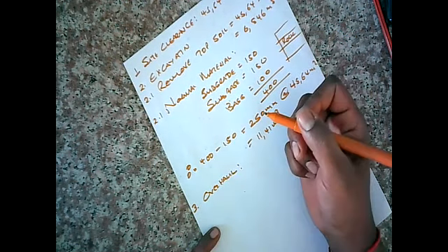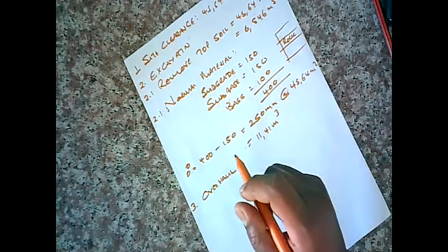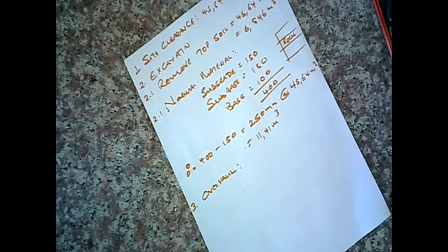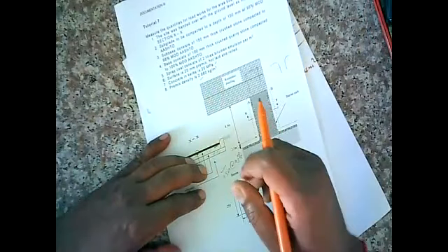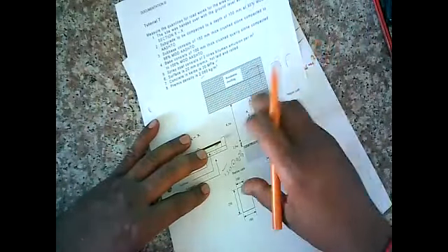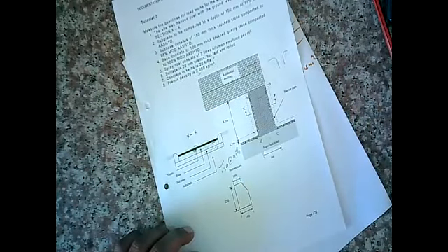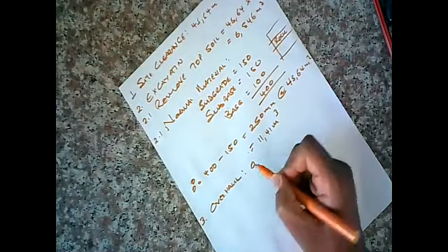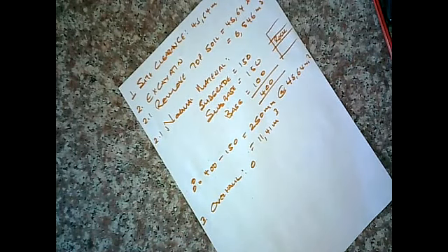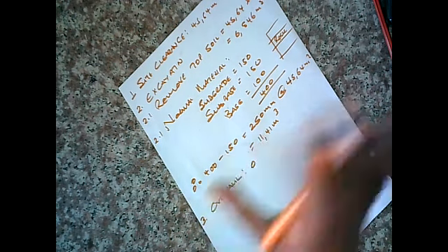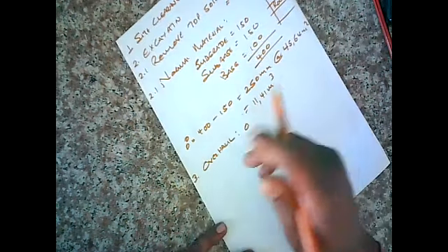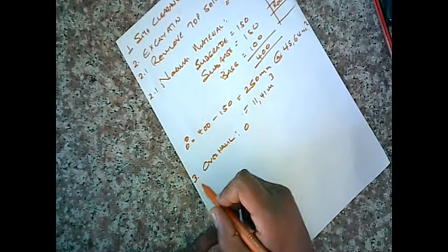Is there a condition for overhaul in the question? We're not given a condition for overhaul. I suspect the homeowner wants to use that extra material somewhere else, so he's not giving the contractor the opportunity to cut it away. So overhaul over here is going to be 0, if you're wondering about that. And if you want to quantify, if you leave it out, that's fine also. I'm not going to attach marks to overhaul.